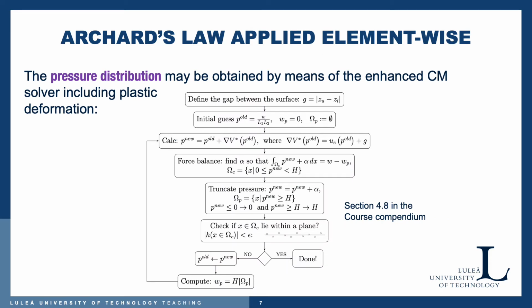In order to calculate the wear depth, we need the pressure distribution. And the pressure distribution we may obtain, for example, by means of the enhanced contact mechanics solver that includes the plastic deformation that we learned about in the contact mechanics part of the course. And here we have the solution procedure described, and refer to section 4.8 in the course compendium for more details on this again.